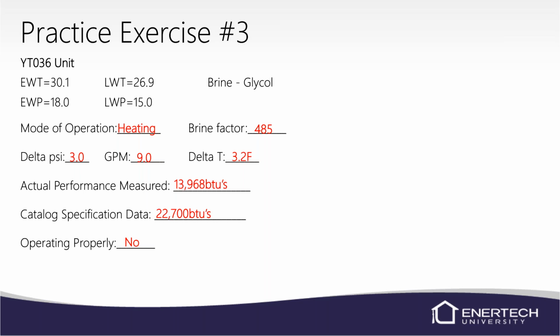So no, at this point, you would have to move on and diagnose this one further. It may take you putting the refrigerant gauges on there, but I would check electrical stuff first and rule that out, and then put my refrigerant gauges on there. Could have a TXV issue, or it's low on refrigerant or something like that. So this one, again, not operating properly. It's not within 10%.